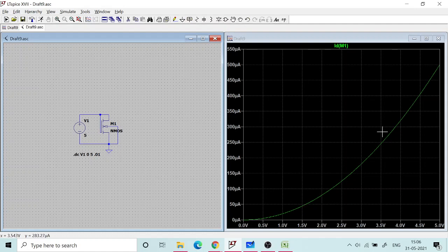So it's like a parabola, and we will see the derivation for this parabolic relationship between VGS and IDS. But right now, that is only one curve. You cannot have multiple curves for this, because we are taking saturation current which is independent of VDS. So you just need to apply a voltage which is enough to saturate. That's the only criteria. And the simple way of doing it is to make VGS same as VDS.